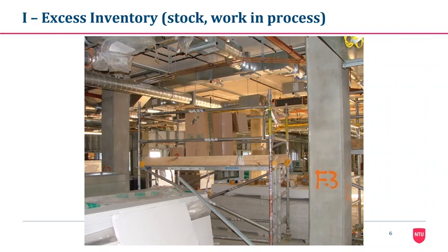Lots of tasks started can make it difficult to finish as resources may not be available. Starting work out of sequence and without screening all 8 flows to remove constraints is called making do, a source of waste in construction identified by Koskela.